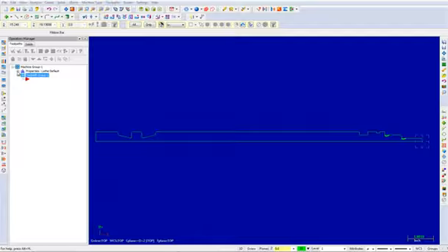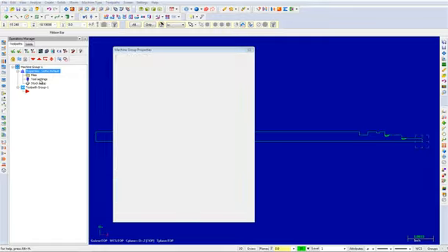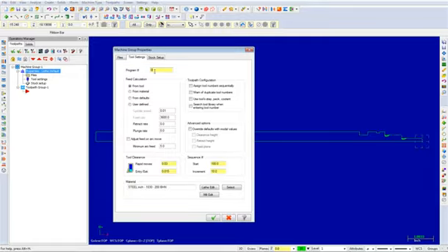Select plus next to Properties and pick Tool Settings from the expanded list. Input a program number of 6 and enable Assign Tool Number Sequentially and Warn of Duplicate Tool Numbers. From here, select the Stock Setup tab.